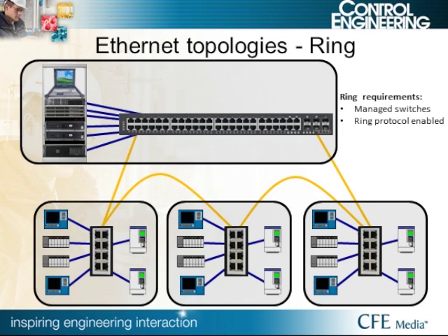The 2 to 3 second network blip isn't a problem when checking email or surfing the web, but control protocols will time out in 120 milliseconds or less. That is why many industrial switch manufacturers have their own proprietary protocol with ring heal times that are under 30 milliseconds. What no ring protocol can compensate for with this topology is if there are two failures on the network.